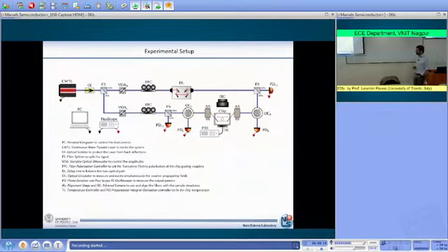Here is a short overview of the kind of experimental setup that we are using in order to measure those microring resonators. Just to give you an idea, here is where the microring resonators are placed. You see the microring resonator, the waveguide, the coupling, and in this case you have gratings to input and output the light from the coupling. Since silicon is a semiconductor, the properties are very sensitive to temperature.